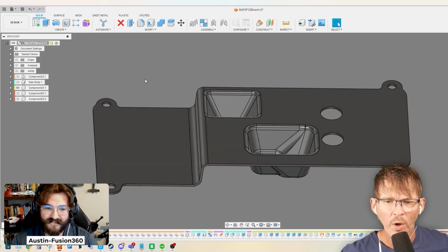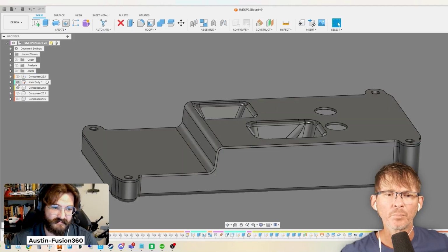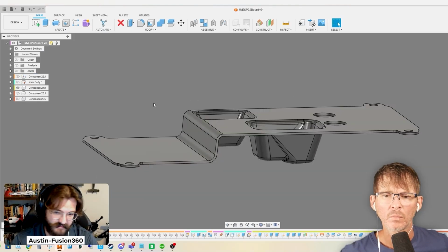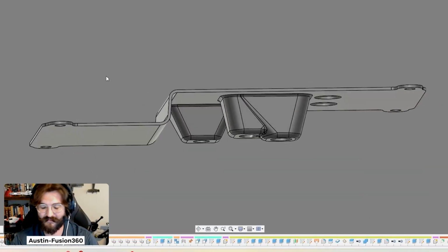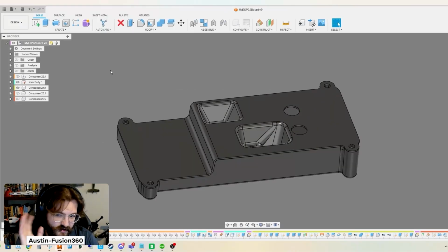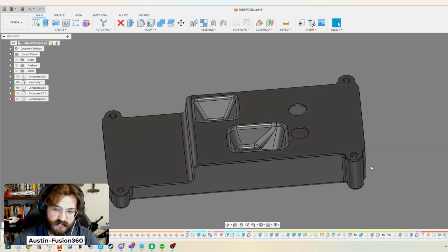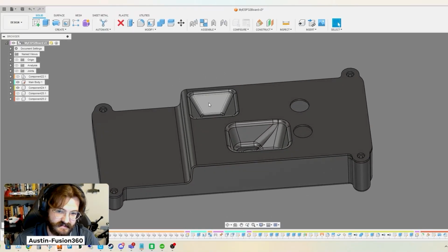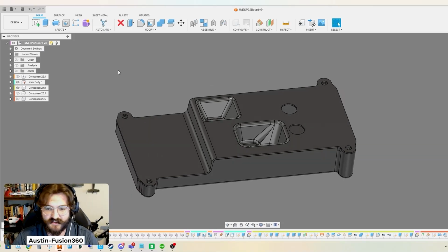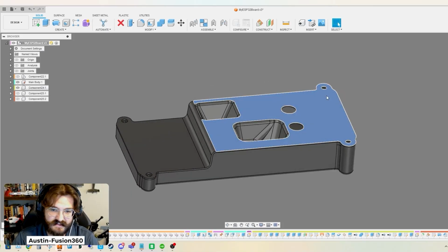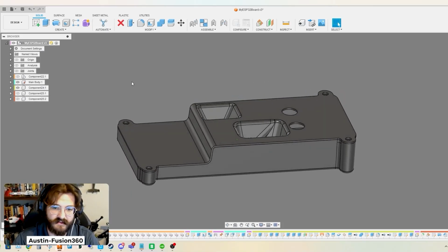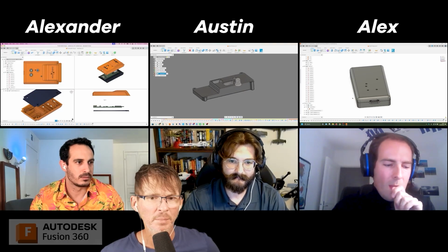I thought you were doing 1.5 millimeter. I was for the body, and then when I made this part it became 0.5 millimeter thick. The saving grace here could be that because it's supported by this outer wall and it has these ribs here, there could be some structure there, but more than likely this would have to be updated to be thicker, you know, 1 millimeter or something like that. Alex, do you want to maybe go through yours now?